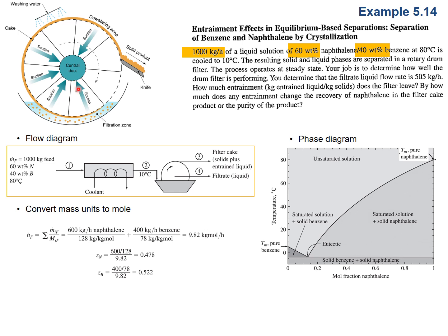Of course, on the surface of the drum we have a filter, so only the liquid part is sucked into the central duct. Then on the surface of the drum we find the filtrate, or solid material films. This drum is rotating, then the film is accumulated.